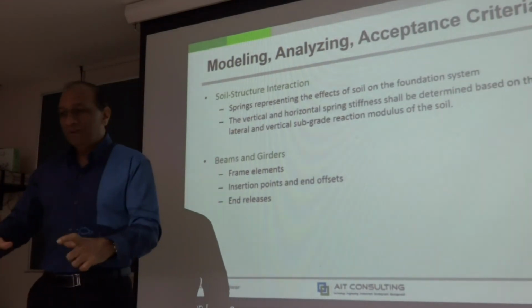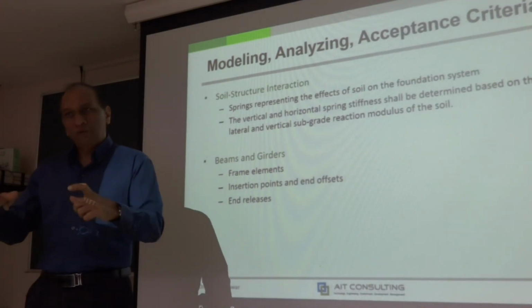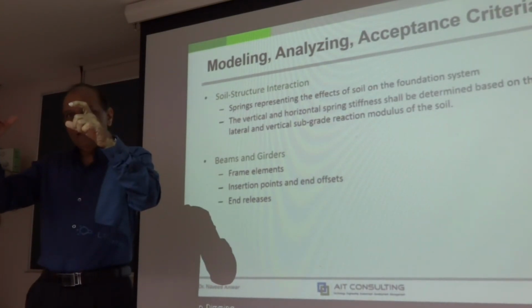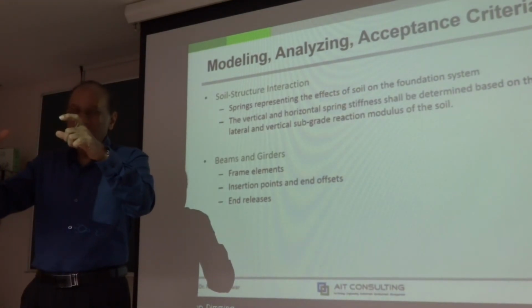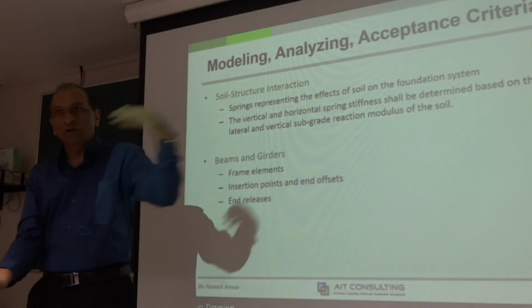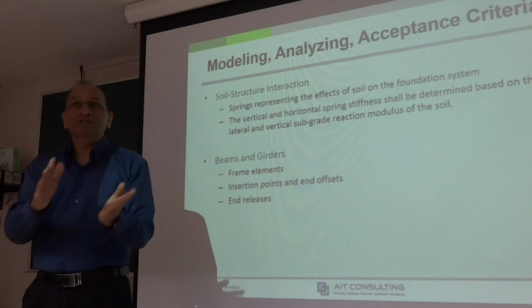The model should be built floor by floor, loaded by the dead load floor by floor, completed the entire building, apply the live load 25%, assuming that not everybody is there in the room, and then apply the earthquake at the ground the way it is shaking, not apply forces. Shake the ground, and then see how the structure is going to move.